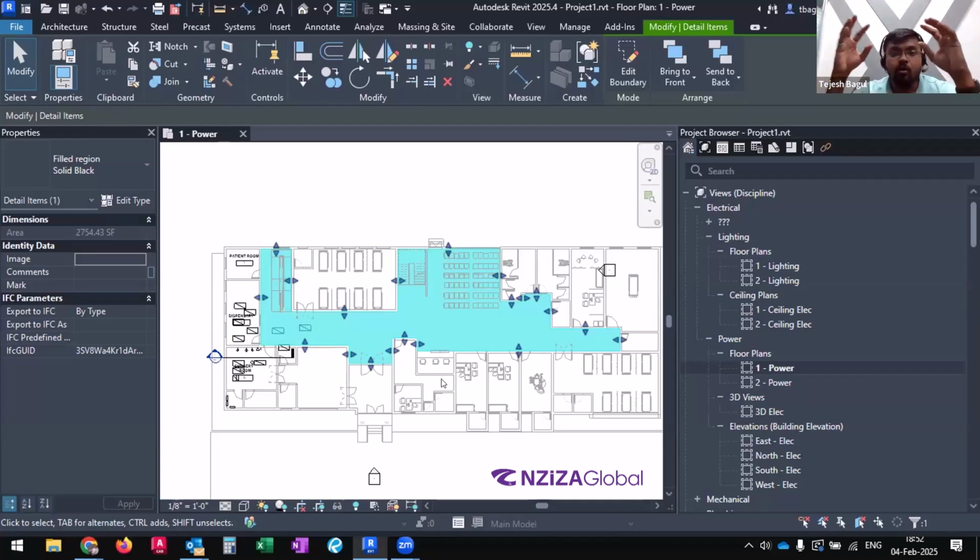That is because only particular light fixtures will be on when there is a power failure. And again, we are just talking about the spaces where you have an exit path of egress. This corridor is 2754.43 square foot. Now we have gotten the area. Area was in the denominator, and on the top was the lumen. The division of both of these numbers was multiplied by the efficiency factor, and it gave us the foot candle.